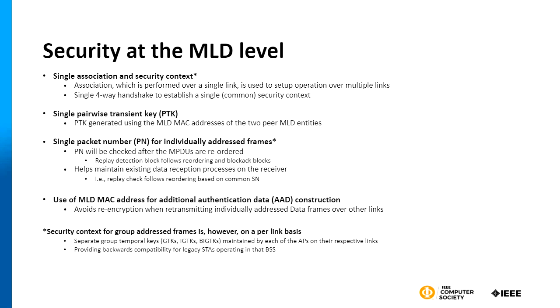So then we have a few questions related to the physical layer. The first one is more on the higher bandwidth, because you mentioned that in Wi-Fi 7 we now have 320 megahertz bandwidth. The question from the audience is that usually higher data rates have lower range. For 320 megahertz, which is a higher data rate, how does it have better range? Oh yeah, so that is by the repetition that we discussed briefly.